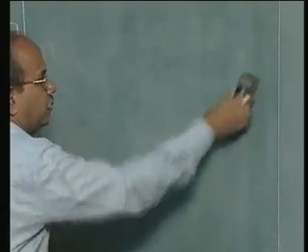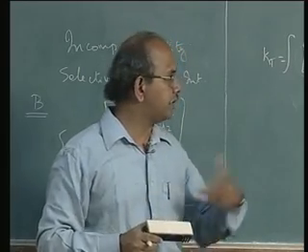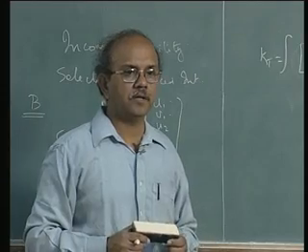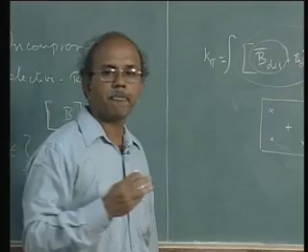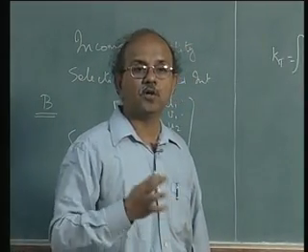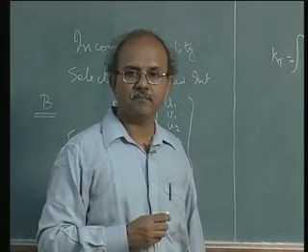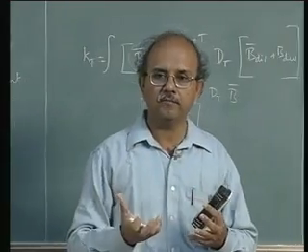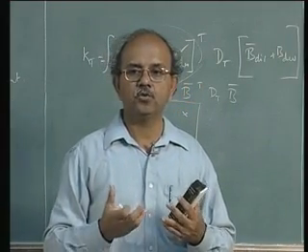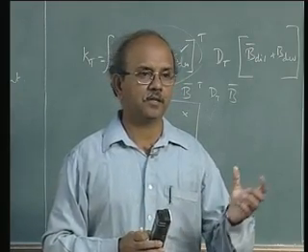One comment is in order. There are other types of formulations as well, and one of the comments passed in my earlier course is that the strains have to be enhanced in order to meet certain demands, for example in bending. An ordinary quadrilateral element cannot take bending, and hence you have what are called enhanced strains to take care of that, so that it can bend.